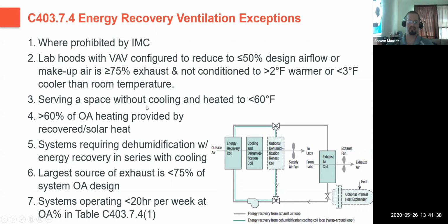Serving a space that is not cooled or that does not have cooling and is not heated above 60 degrees. You do not need to have energy recovery. If greater than 60% of your outside air is heated by some kind of recovered heat or solar heat, then you do not need energy recovery. Systems requiring dehumidification with energy recovery in series with cooling.